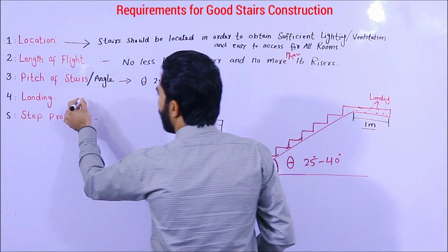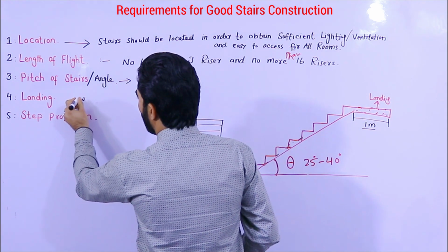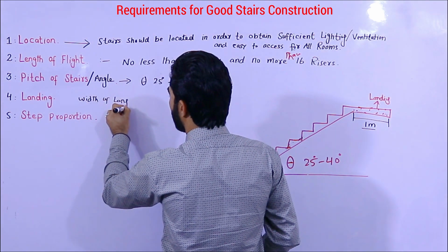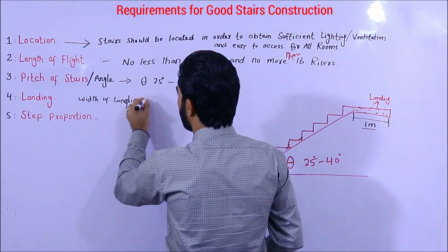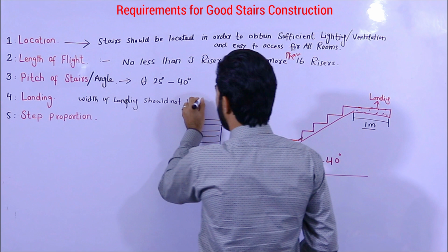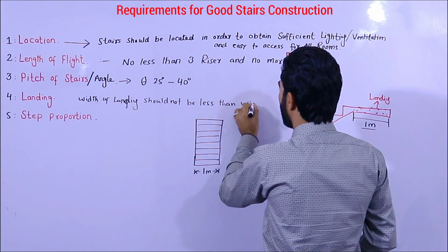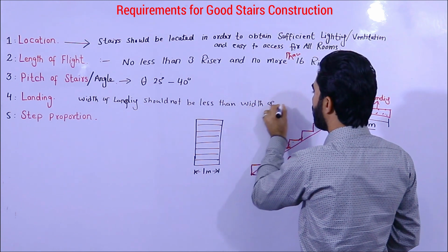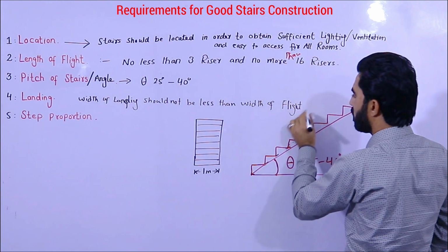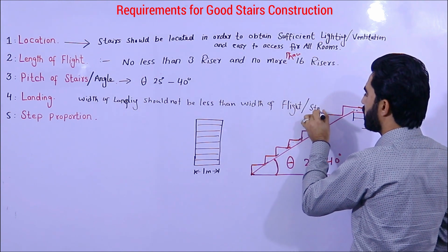Means the width of landing should not be less than the width of flight, or width of stairs.